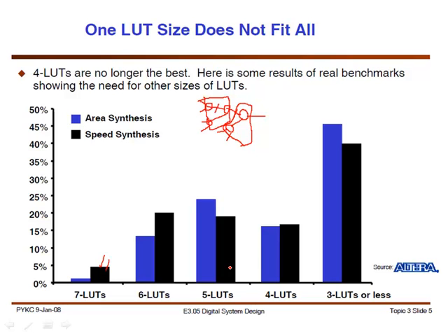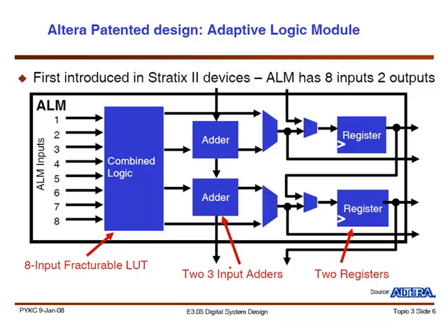If you remember, for the 7 LUT, for example, you would use two 6 LUTs in parallel, but you're sharing the exact same inputs to both of them. So that means the extra flexibility that the FPGA provided is being wasted now. Now, if you look at Altera's version of the CLB, the CLB in Xilinx, the configurable logic block, has the same functionality as the ALM.